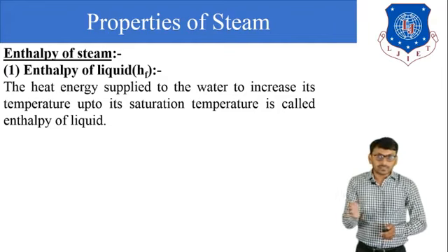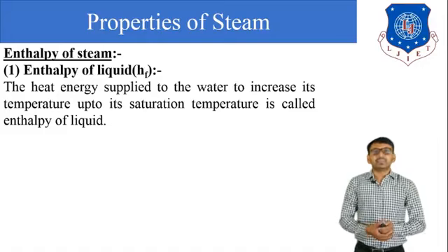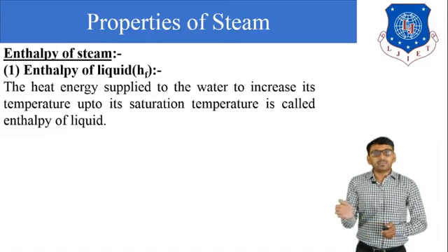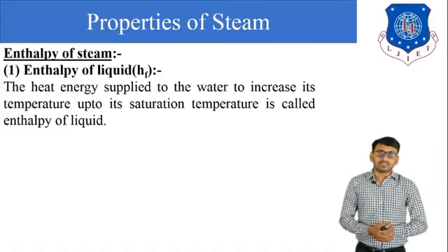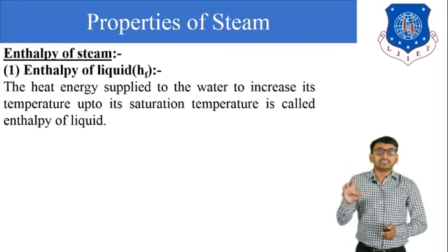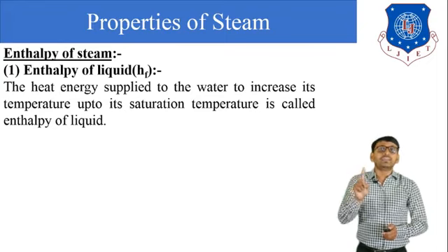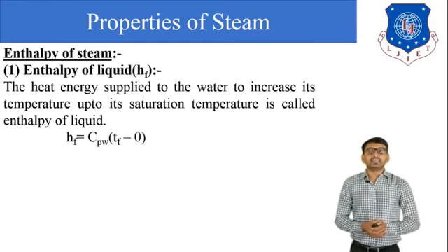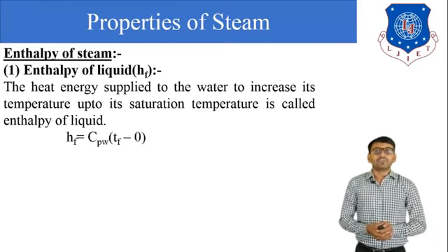So when heat energy is supplied to liquid or water, its temperature increases up to saturation temperature. This heat energy is called enthalpy of liquid, and the formula is Hf equals Cpw times Tf minus 0.